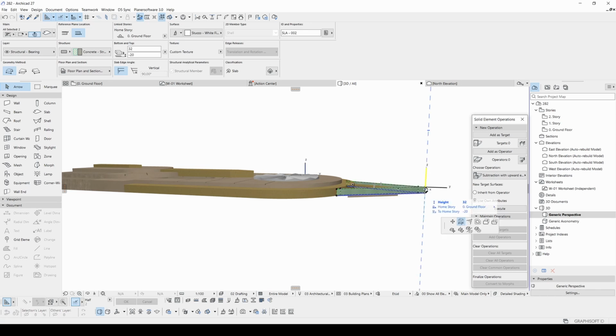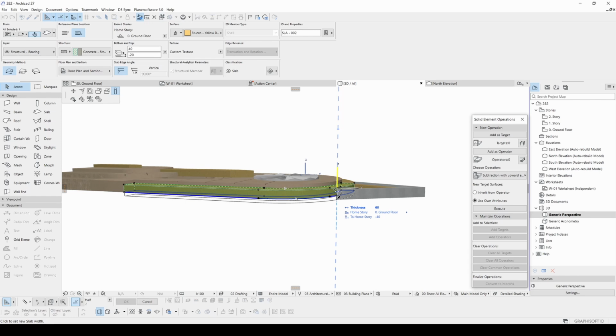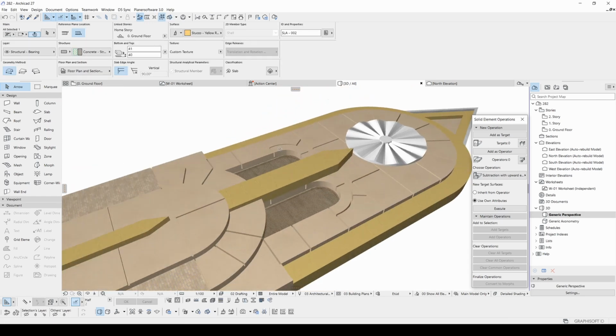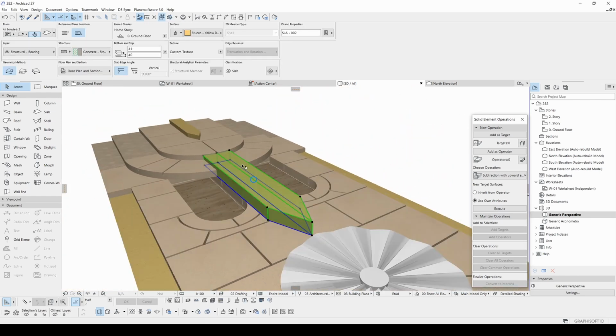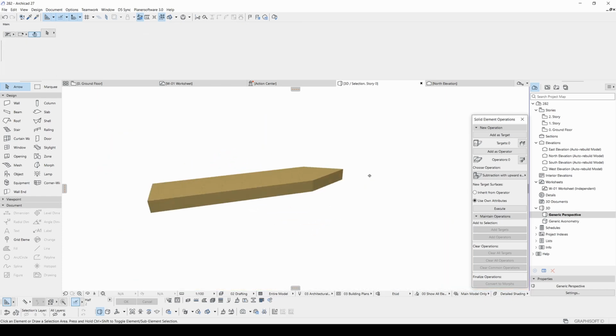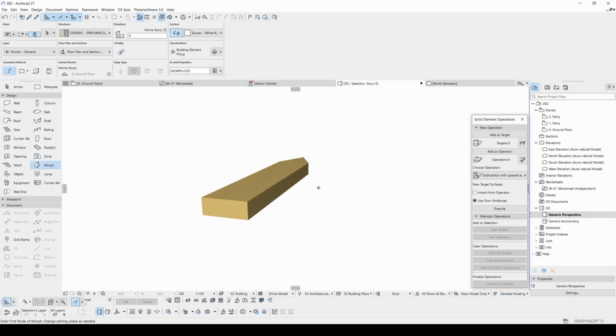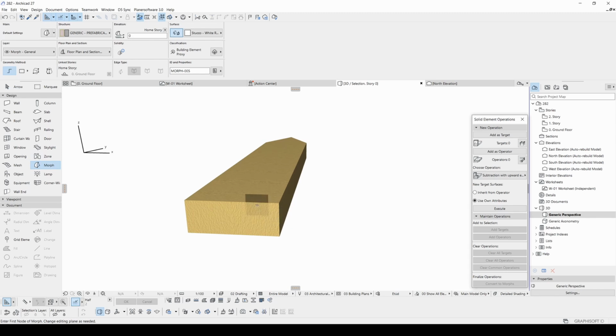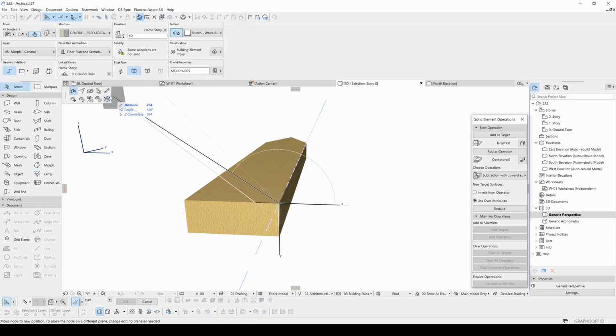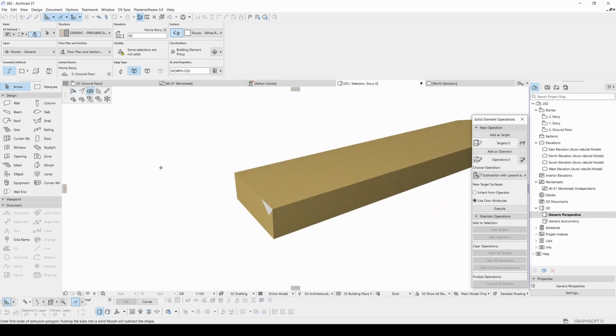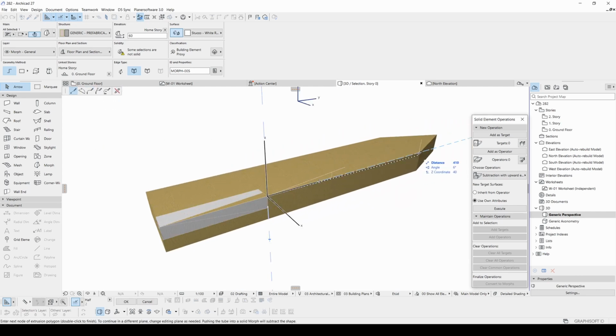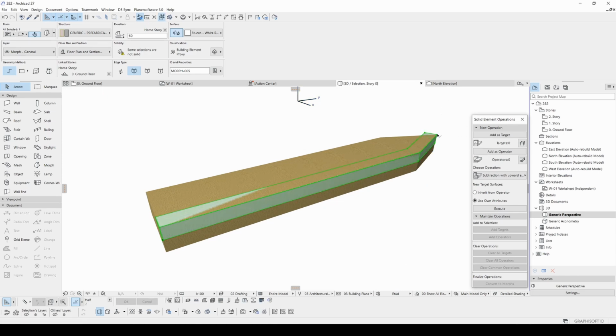For the final, if you want to make this thicker, you can follow these steps. And to make this better, you can chamfer this nose. We will select this and hit F5. And after that, we will click Morph. I want to chamfer from this corner, therefore I will create a triangle, something like this. We will click this and click this corner and click tube. It will be very easy.